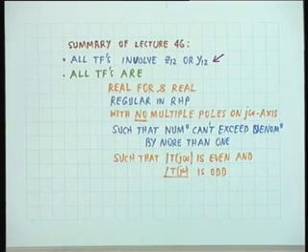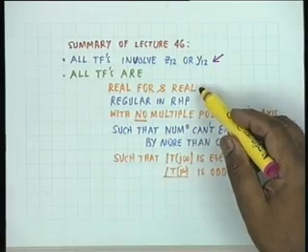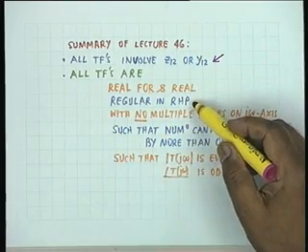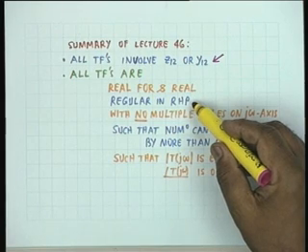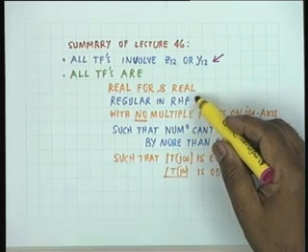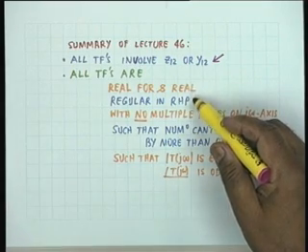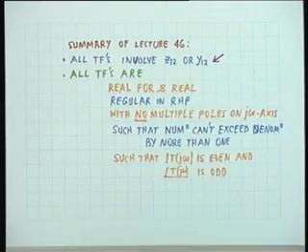We have assumed the networks to be reciprocal, therefore, it is either z21 or z12, it does not matter, they are equal, they are identical. We showed that all transfer functions are real for S real. They are regular in the right half plane. Does this mean something to you? Regular in the right half plane means there are no poles in the right half plane. Regularity means absence of poles, no poles in the right half plane.